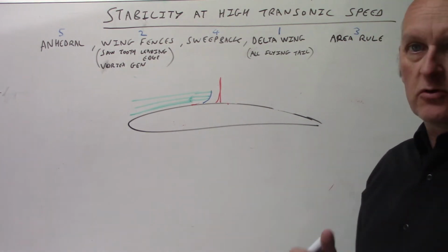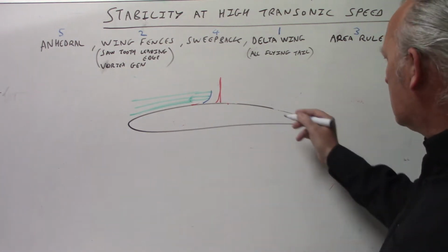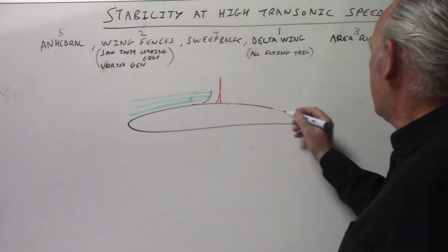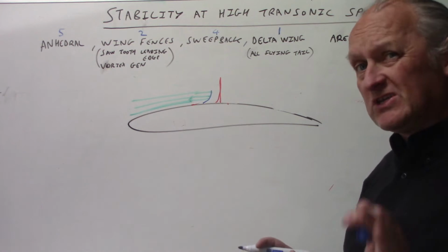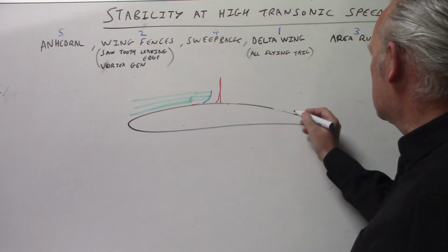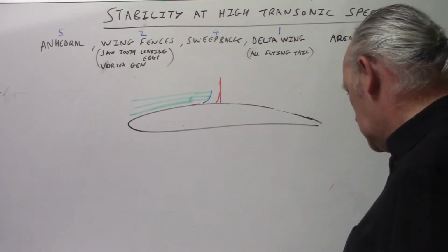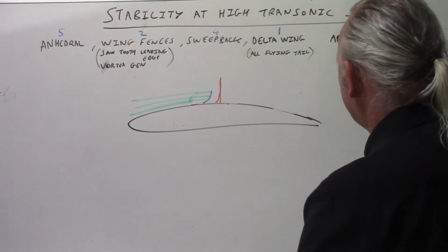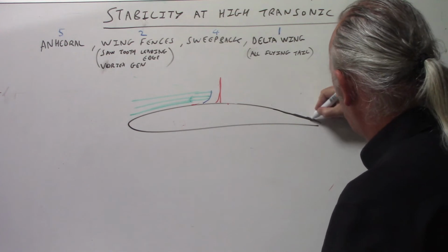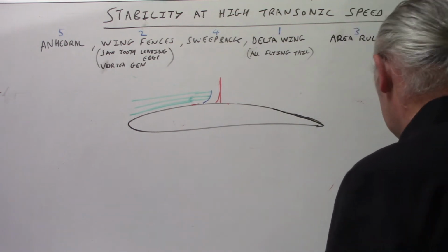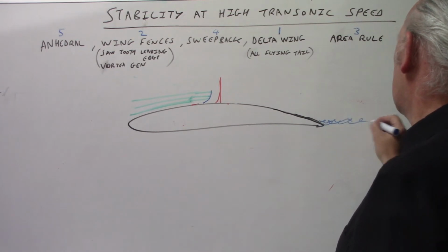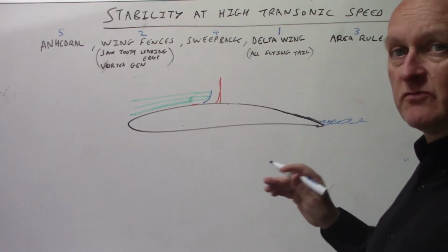We can come across a thing called a shock stall, which we'll do in a minute. The first thing we've got is standard separated flow, which isn't a shock stall, but it's similar: air becoming separated just because you're going too fast. As you go faster and faster, the air will start to become turbulent at the very trailing edge, at the very back.